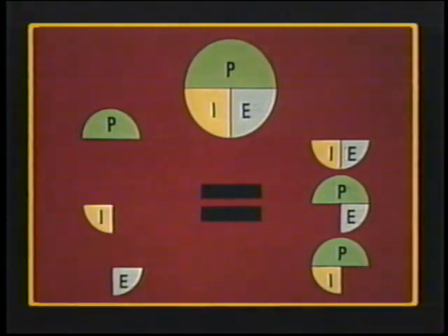The same type of circle arrangement we use to visualize the voltage-current-resistance relationship may be used with power, voltage, and current. Power equals voltage times current. Current equals power divided by voltage. And voltage equals power divided by the current.